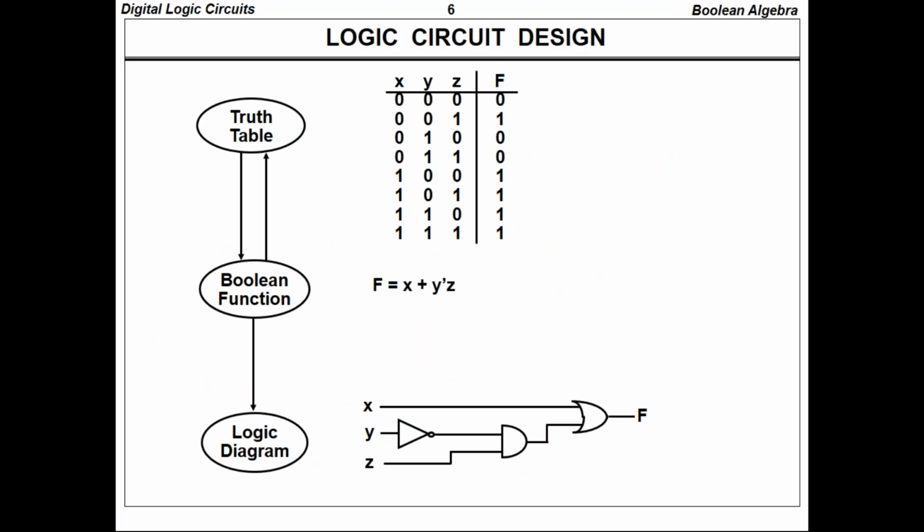If you consider this logic, you have three inputs x, y, z, and the output is f, which changes like that. If I want to generate the equation, we have to form the algebraic expression. For x bar y bar z, the outputs which are 1 we have to consider alone. So here f will be 1 for the values 1, 4, 5, 6, then 7. These values contain the output as 1.